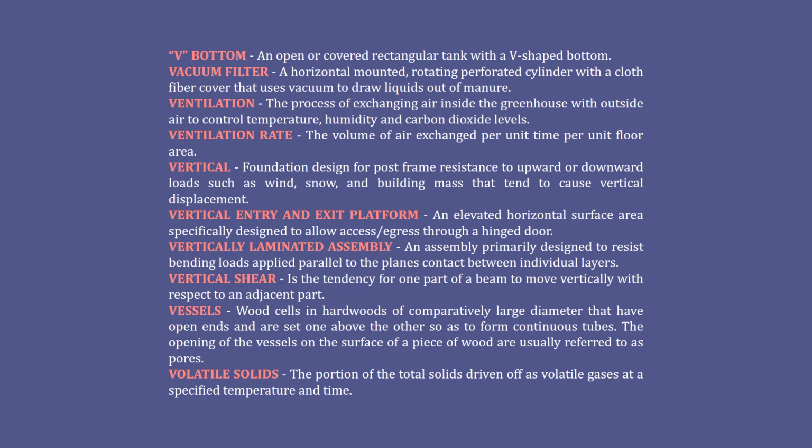Vertical. Foundation designed for post-frame resistance to upward or downward loads such as wind, snow, and building mass that tend to cause vertical displacement. Vertical entry and exit platform. An elevated horizontal surface area specifically designed to allow access and egress through a hinged door. Vertically laminated assembly. An assembly primarily designed to resist bending loads applied parallel to the plane of contact between individual layers. Vertical shear is the tendency for one part of a beam to move vertically with respect to an adjacent part.